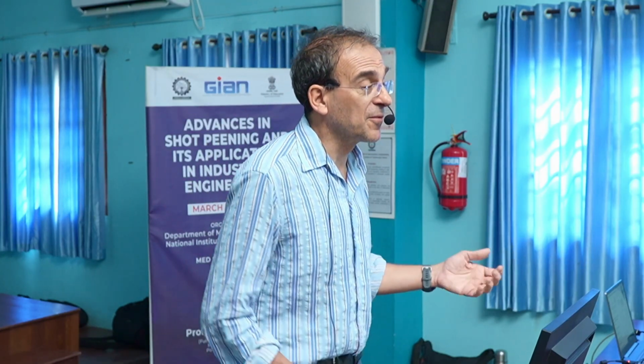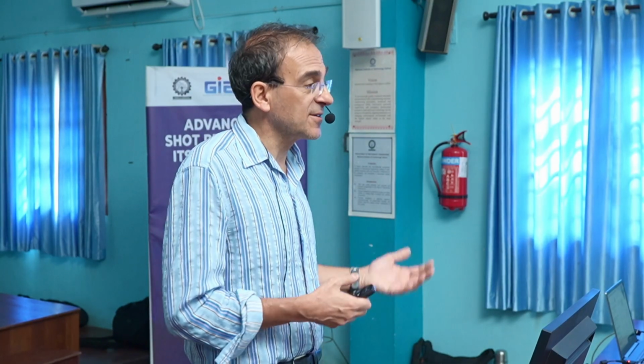But does it use the Kelvin model or Maxwell model for material damping? That is another option. And indeed, for damping, we can introduce some value just to dampen the waves, or we should perform some damping tests to determine the structural damping of the material, or we should rely on reference values. Thank you. You're welcome.